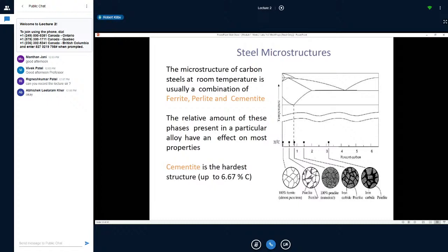So as the steelmaker has more carbon, the individual crystals are saturated with carbon, and it starts to fill in the grain boundaries and compress these crystals. When we get to just a little bit over 2%, that's the end of steel. Steel can't have more than 2.1, 2.08, depending on your reference. And don't worry about memorizing this. We're not going to ask you to know it for an exam. But once we pass here, this is cast iron.